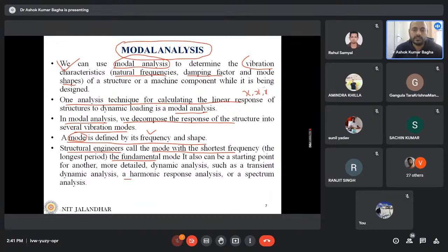So in this lecture, I just want to say that if you want to work on composite material, or if you are choosing any structure, please initially apply harmonic response analysis. First of all, apply the harmonic excitation on the structure. Because when you apply harmonic excitation on the structure, the excitation is known to you. So accordingly, find out the response. If you are exciting the structure at, let us say, 786 hertz, the response should be at 786 hertz.